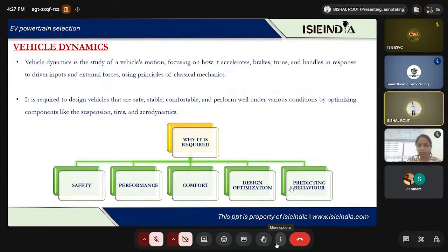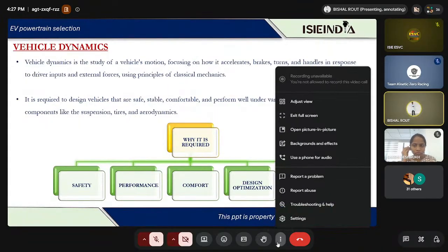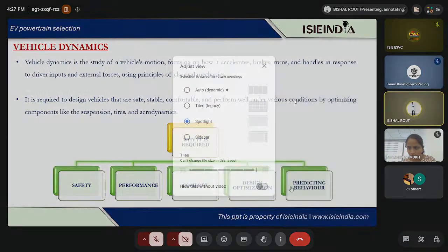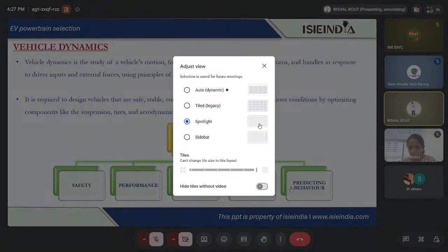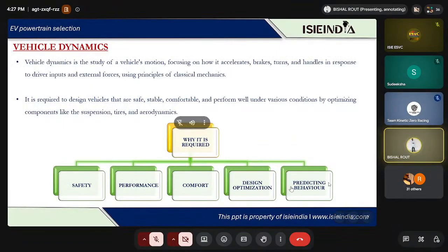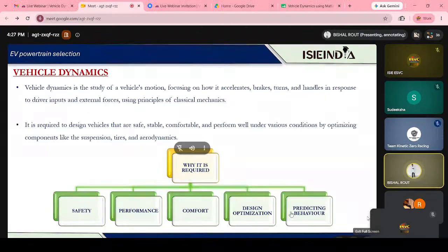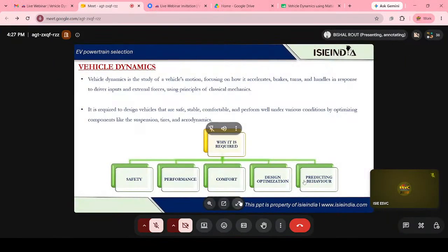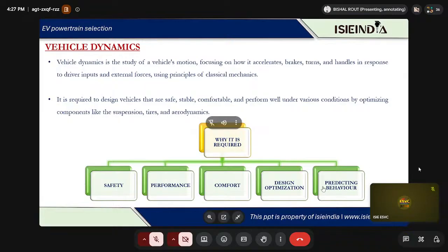I'm actually on the part of design optimization, right? I told you that automotive engineers have hundreds of design variables. It is not only one design variable you have; they have hundreds of design variables. Some of them are vehicle mass, center of gravity height, front and rear weight distribution, tire size, even the tire stiffness, the spring stiffness, damper coefficient, steering ratios, motor torque, brake distribution, battery locations, right? Aerodynamic coefficient, right? So changing one parameter can influence several vehicle characteristics, right?